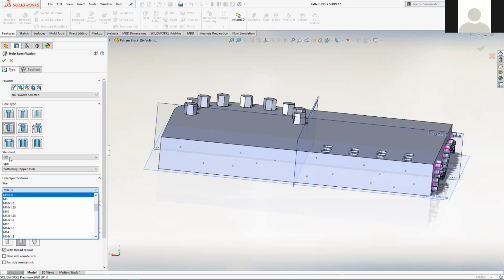So in the ISO standard, you can see I've got a few variations of M12. Generally, what you would refer to as standard M12 or coarse thread would just be the one that doesn't have the pitch after it. So I think on M12 it's 1.75, or maybe it's 2, the pitch. I'm not entirely sure.